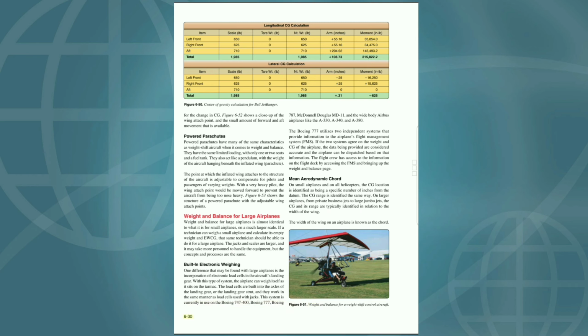The width is greatest where the wing meets the fuselage and progressively decreases toward the tip. In relation to the aerodynamics of the wing, the average length of the chord on these tapered swept-back wings is known as the mean aerodynamic chord, MAC.